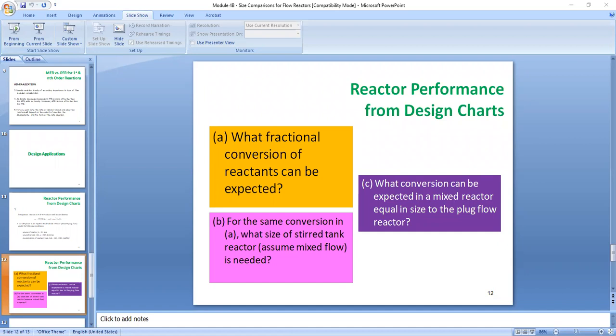So we're given here the aqueous reaction of 1 mole of A reacting with 1 mole of B, forming the products with known kinetics, which is second order. You have 500 times the concentration of C sub A times C sub B as the rate law. Now this is to take place in an experimental tubular reactor, which is to be assumed as the plug flow reactor under the following conditions.